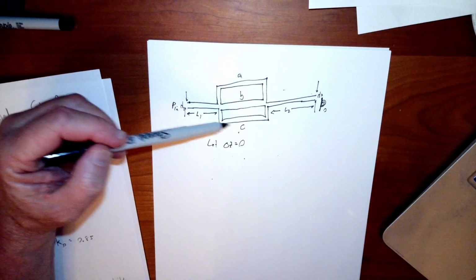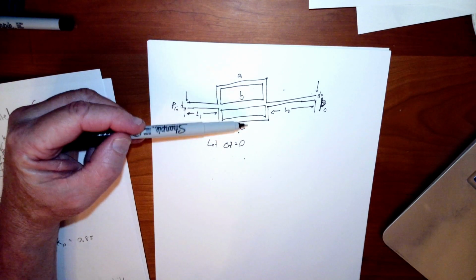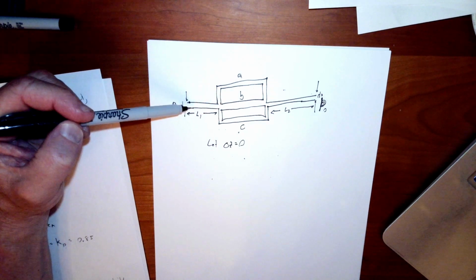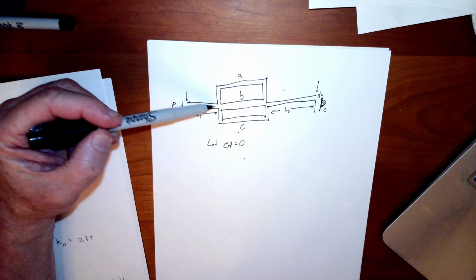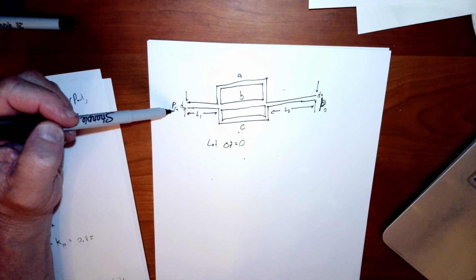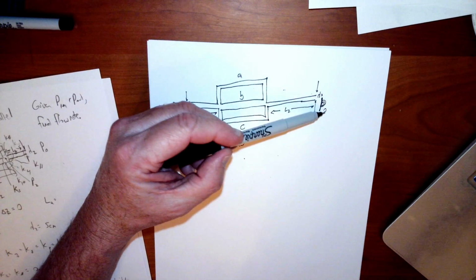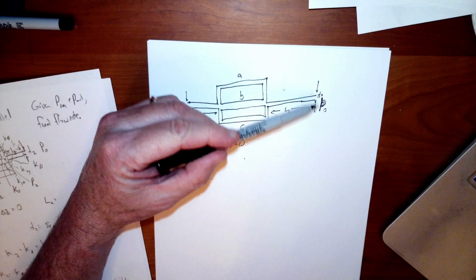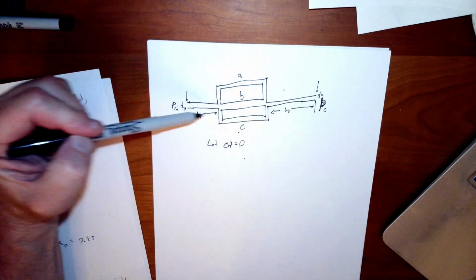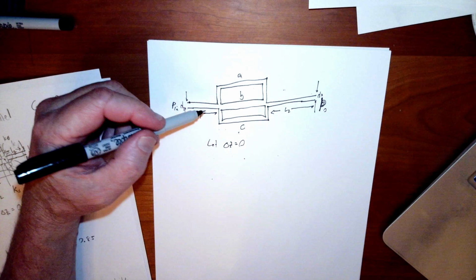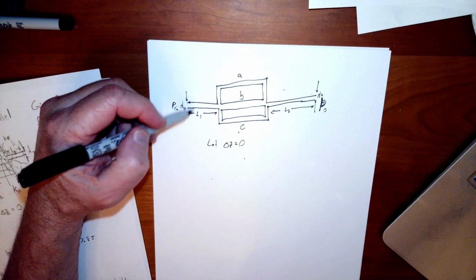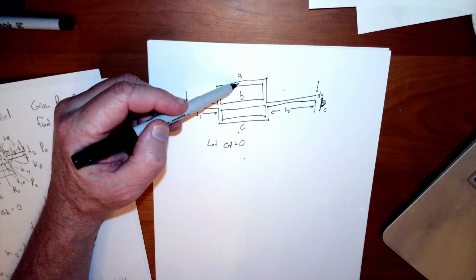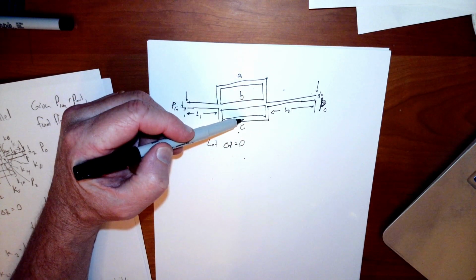This problem, compared to the last problem, has three pipes in the branching network. We've got A, B, and C here. We've got an inlet pipe that is non-trivial in length, so we don't know the pressure right at the junction here. We know the pressure at the inlet and the pressure at the outlet, but both are separated from the junctions by significant lengths of pipe, L2 and L1. The problem therefore has a lot of different diameters. It's got the diameter of this pipe 1 section, the diameter of the pipe 2 section, diameter of pipe A, diameter of pipe B, diameter of pipe C.